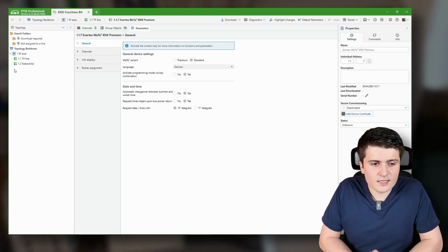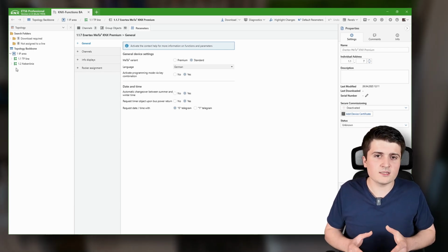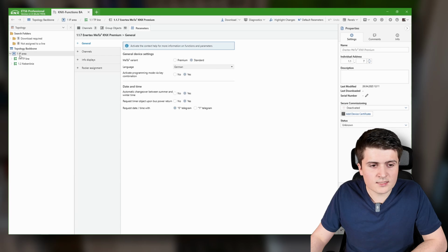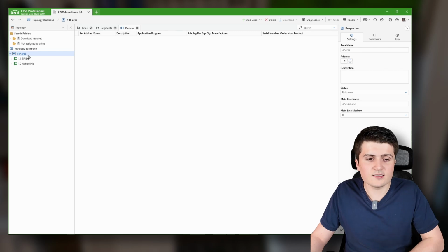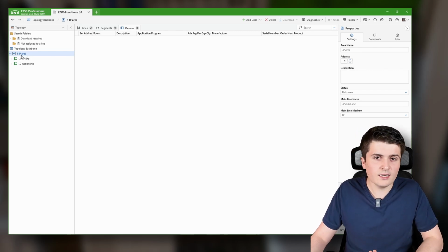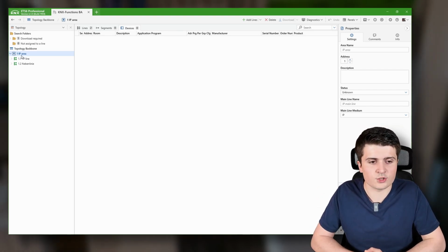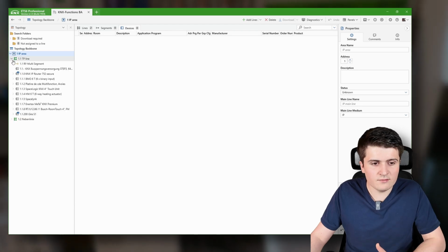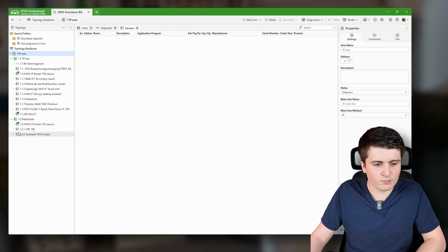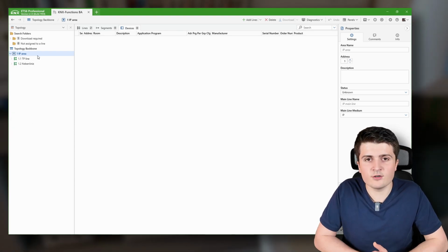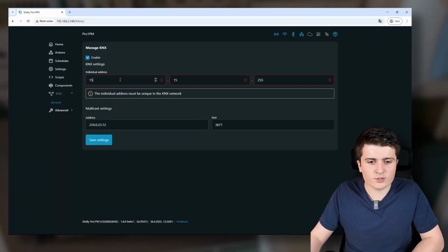are each connected with a KNX IP router. That being said, in my case the Shelly device, as it's not a KNX twisted pair device but instead a KNX IP device, will sit here in this area, the area 1, the IP area. And devices that are sitting in this IP area will have the physical address 10X, so any number on the last digit. Because on the first line, the twisted pair line, all those devices have 1.1.x, here we have 1.2.x, but in our IP area we will have devices with 1.0.x. And so that's what I want to set up here.